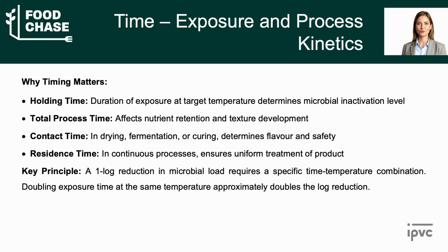A 5 log reduction means we have killed 99.999% of the target microorganism. To achieve that, we need to hold the product at the target temperature for a specific amount of time. That is the holding time. If we shorten the holding time without raising the temperature, we achieve a lower log reduction and the risk of survival increases. If we extend the holding time, we overprocess and waste energy and nutrients.